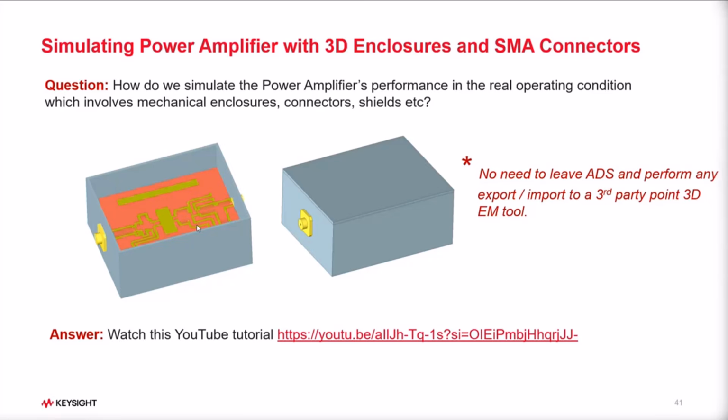As you saw, you have been taking a single device from DCIV all the way to finish the amplifier and perform modulation analysis. So it makes sense that under this assembly condition, you can do one tone, two tone, Modulation Explorer, DPD Explorer. You can do all sorts of analysis in a complete assembled mode so that there is no surprise when you end up assembling this, right?